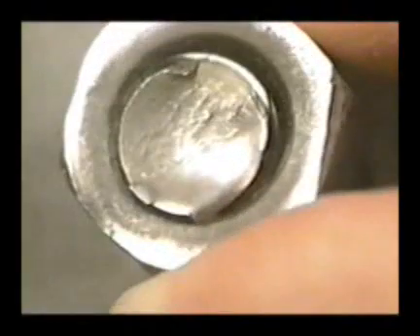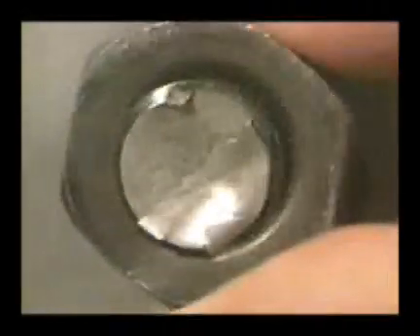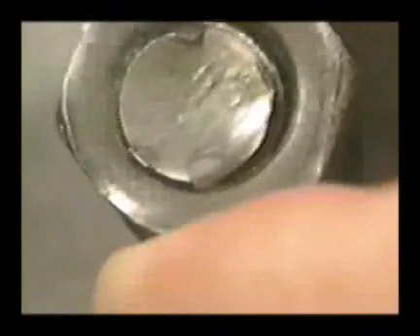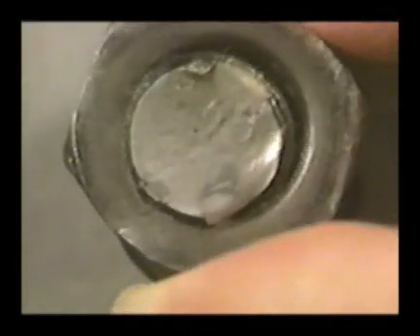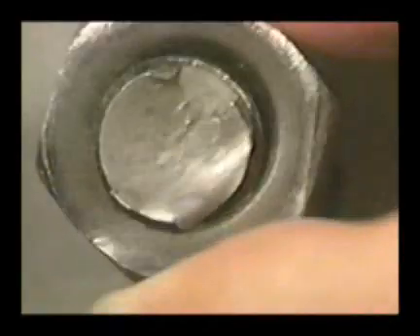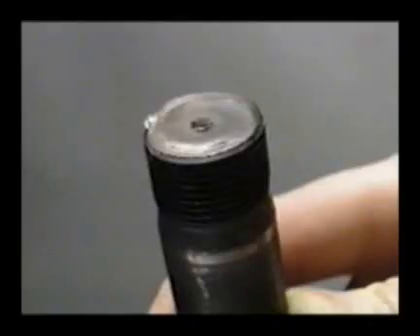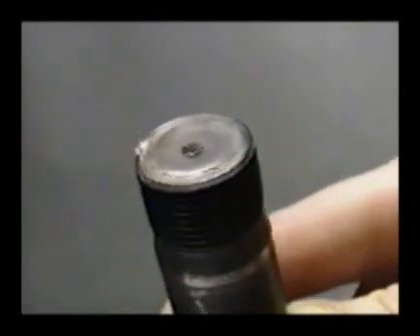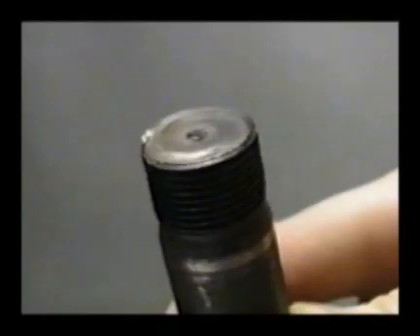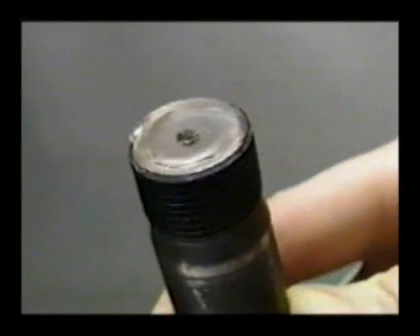Not all ductile fractures produce a rough surface. Under shear loading, parts fracture by sliding past each other. This produces a fairly smooth texture, best described as satiny or smooth and silky. Ductile fractures produced by torsional loads can occur in either the transverse or longitudinal shear plane. If fracture occurs across the part, it is called transverse shear.